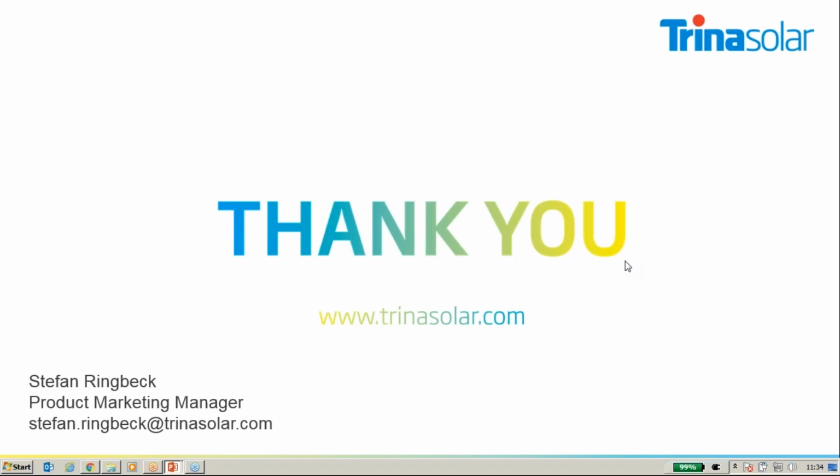There's a question: bifacial on a residential home, does it make sense? For residential, it depends on where you're installing it. If you're installing bifacial on a roof parallel, then the benefit will be close to zero because you don't have enough space and not enough inclination to have the surface underneath as a reflector. So you need a certain distance to ensure that the reflected irradiation, that reflected energy, can energize the complete module surface on the back side.